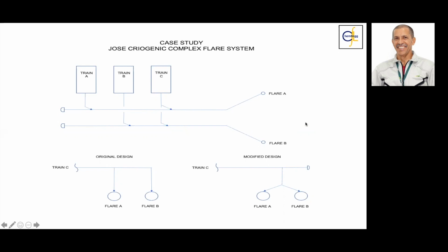Okay, and then, you may need, for the capacity, 4 subheaders for burners, but you talk to your flare manufacturer and you say, okay, I am thinking of an expansion, I will need more capacity, and then he can leave 3 or 4 more spaces to allocate for other burners. So for ground flare, it's easier. For elevated flare, it's not that easy.